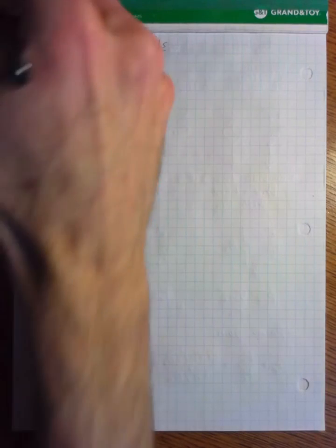Typically, when we work with values that vary over a huge range, it's useful to look at them in a log scale, because it tends to blow up the smaller values and compress the larger values. And decibels, or more specifically bels, are units that just allow us to do this. A bel is the log of a power ratio. So whenever we're working with bels, we're always working with powers and we're always working with ratios.